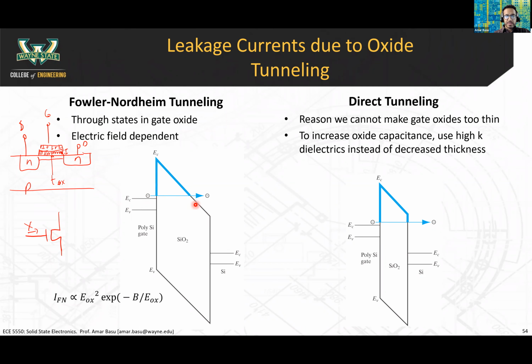Remember, oxide could have a conduction band. The conduction band might be really, really high up because the oxide is an insulator, right? So there's a big gap between the Fermi level and the conduction band. So this could be very high up. But if you apply a sharp gate voltage between the silicon gate and the substrate, you'll bend this portion of the band diagram.